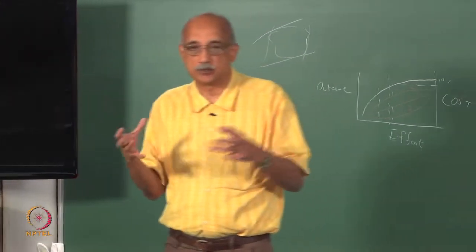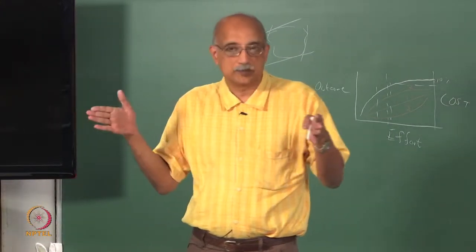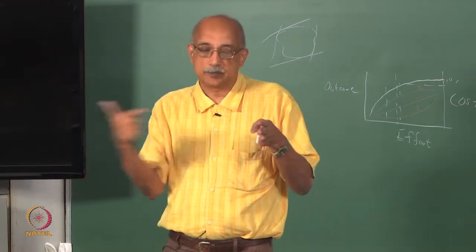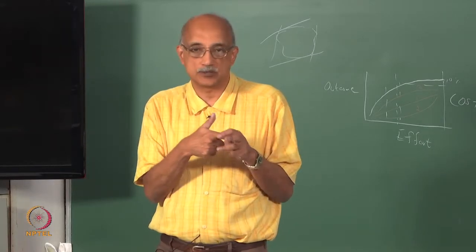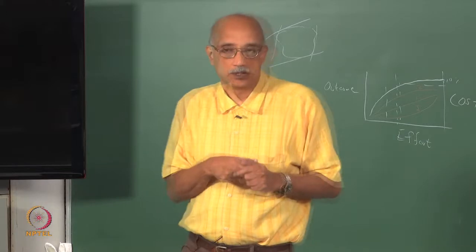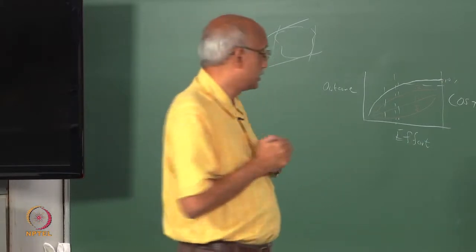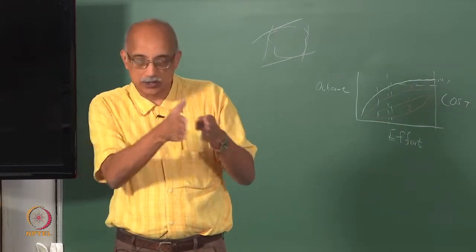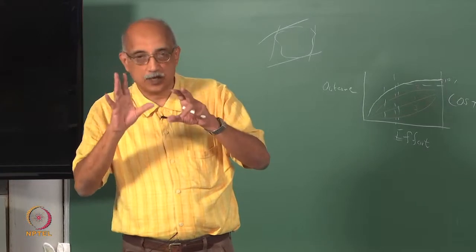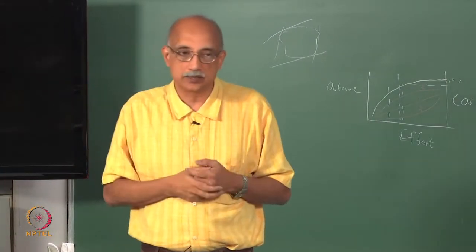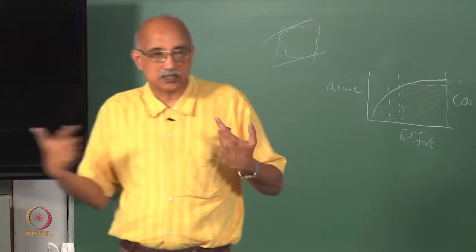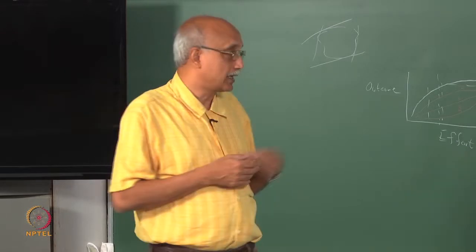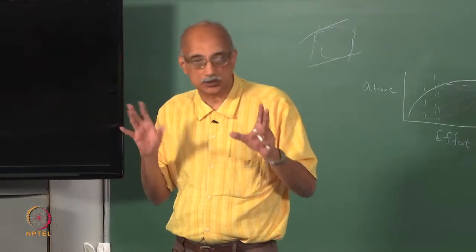So, the bulkier a particle, the longer will be the intercept, right. The needle or dart or whatever you throw will be able to penetrate deeper into the object before it reaches the other side. So, bulkiness can be measured using this type of length of intercept, and of course, it also measures the dimension in one of the directions. So, you can take a same object, rotate it multiple ways and throw dots at it and see what is the distance between the 2 extreme contours of the particle, and that gives you again an idea about the shape of the particle.